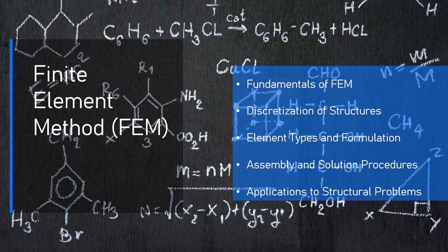The global stiffness matrix, K, is constructed by assembling the individual element stiffness matrices. This involves placing the contributions from each element stiffness matrix into the appropriate positions of the global stiffness matrix based on the nodal connectivity. For example, the stiffness matrix of an individual element, k, is mapped to the global matrix K by using the nodal numbers of the element. Each element's stiffness matrix affects the rows and columns of the global matrix corresponding to the element's nodes.